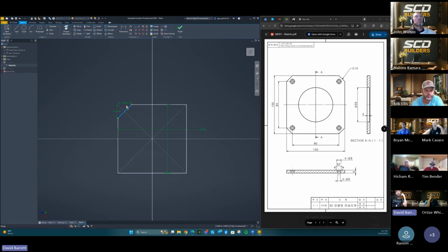So what we're gonna do, let's go back. Let's do that again. Let's type in 10. Then let's click these. Okay, now it looks a lot better. I don't know why it went to that really small one, but we got it resolved. I think what happened is you got to type in the dimension first, in that distance field, then click your lines. Do you see what I'm saying? Yeah, I think that's what happened there. All right, so now we're going to keep going with that.